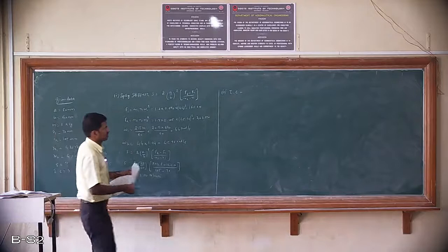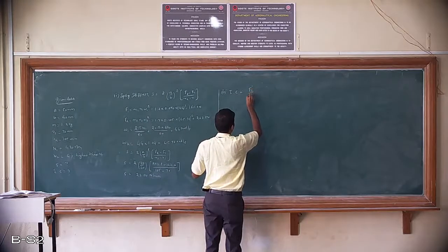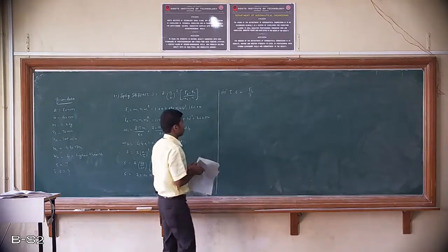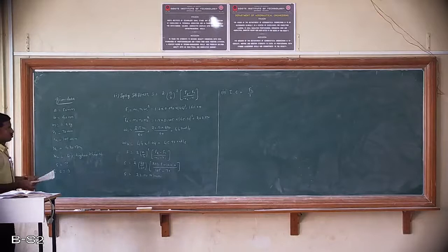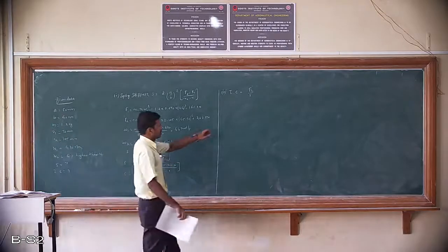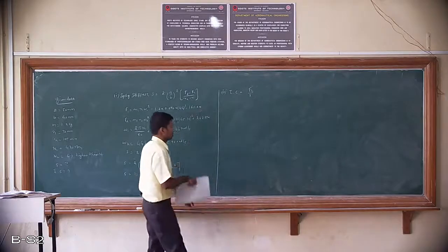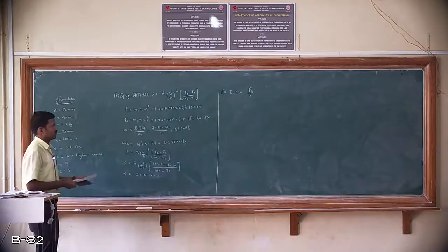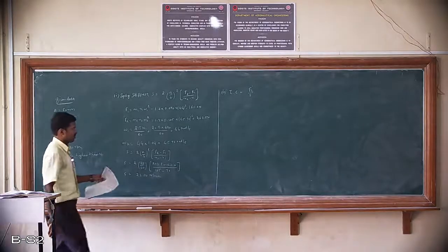That is Fs1 divided by S. So that is the equation to get the value of initial compression. In this equation, S is known, but Fs1 is not known to us. So first we need to calculate the value of Fs1. So how to get the value of Fs1?